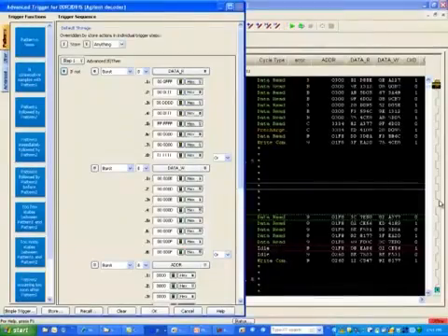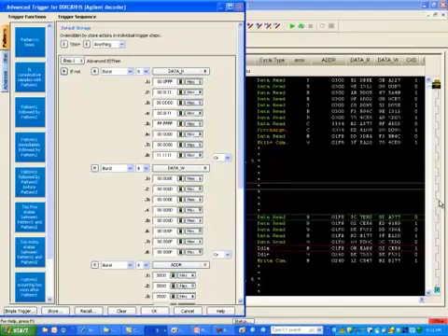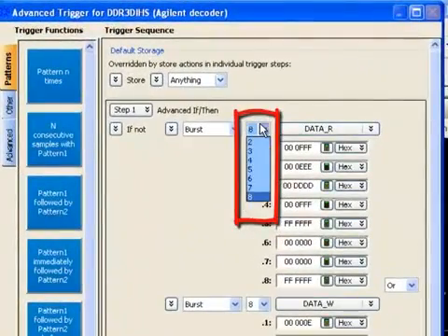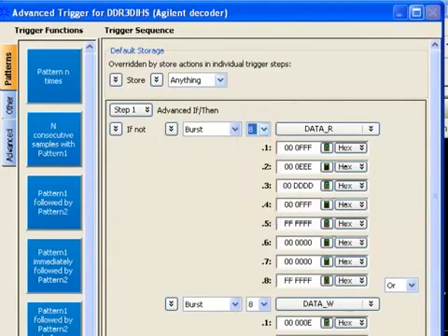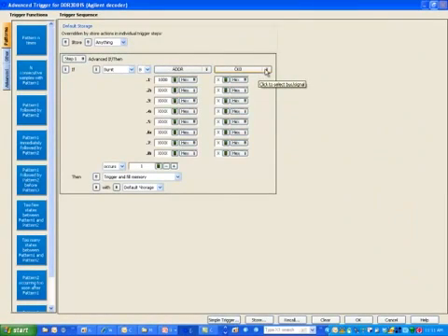Burst trigger is particularly interesting for serial pattern recognition and also for analog to digital converter testing. Burst can be up to 8 events long or as short as 2. Remember, burst triggering is available for any set of signals you might be probing with the U4154A. You can also add additional labels in parallel to build the pattern of most interest for your sequential trigger.